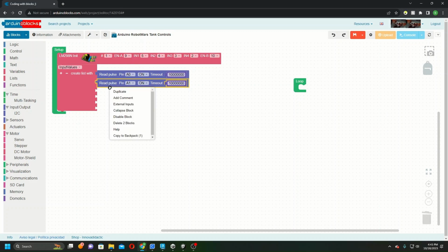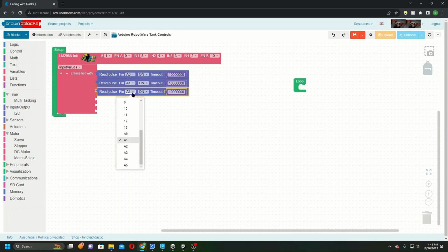Sorry for the stuttering and stammering. I'm going to duplicate again, snap this into place, change it to axis 2. Axis 2, channel 3. It's channel 3, but it's axis 2. This one is on our left stick. It's by default going to be our left, right, or horizontal axis.